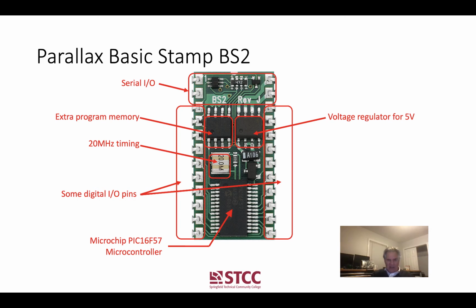It has an actual microcontroller, and it has this 20 megahertz, kind of like a crystal. It's a ceramic resonator, but it's very much like a crystal. It works with a couple of pins on the microcontroller to set up the timing so that the microcontroller runs at a constant rate. And it has a little bit of extra program memory outside the chip.